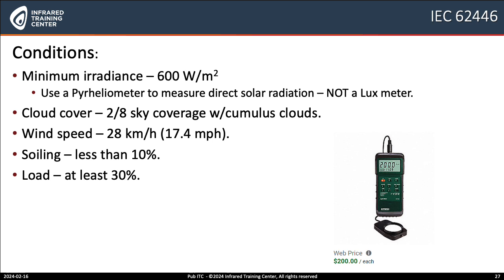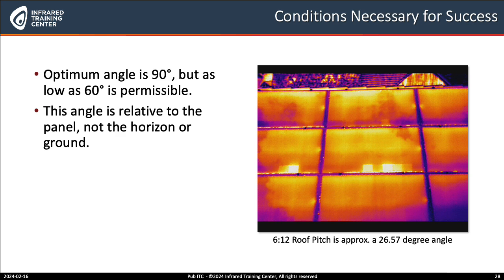So many potential inspection targets that we've got to also keep in mind is cells that are degraded. Whether or not we've got broken bypass diodes within the system, delaminations and cracks in the glass, moisture intrusion, and you'll be able to pick that up very easily. And I'd mentioned already about bird droppings and shadowing. And the glass itself is pretty robust, but sometimes that can even be damaged by the acid or something getting onto it, say fuel. If you've got tractors nearby, maybe diesel fuel being spewed out and just with droplets onto the glass.